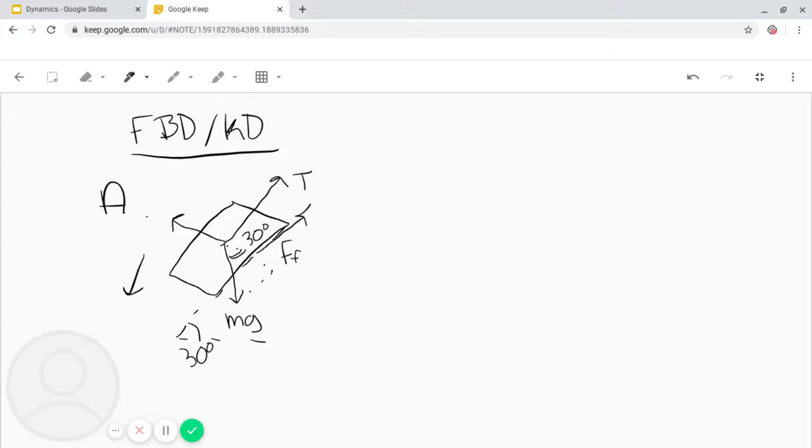So that's just FF, force of friction. And if we find out that that's not the case, and in fact it's traveling the other direction, then we'll just get a negative force of friction, negative tension, etc. So this is equal to our kinetic body diagram, which is this, mass times acceleration. And we can treat the box as a point.